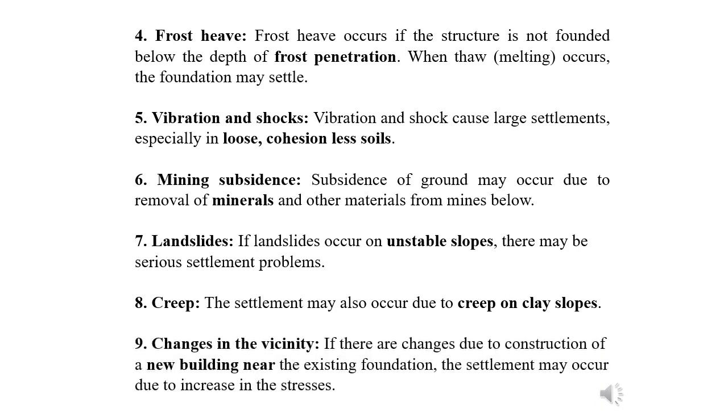Changing the vicinity, that means what? Suppose you have constructed your structure and the depth of the foundation of your structure is up to 3 meters, and adjacent to that, your neighbor is also going to construct a structure. The foundation of that structure he is going to construct up to 4 meter or 5 meter depth. In that case, your foundation may become unstable, and there is a chance of settlements.